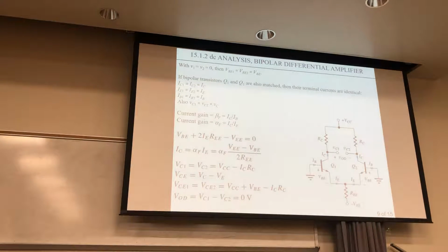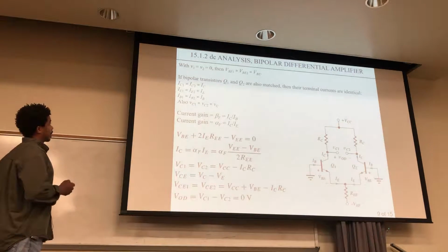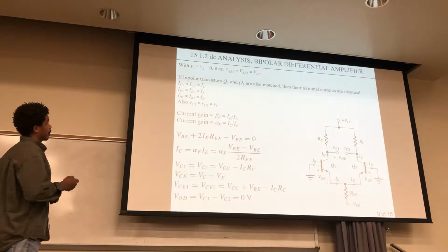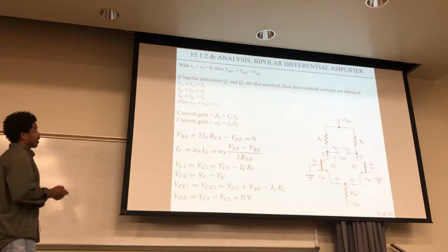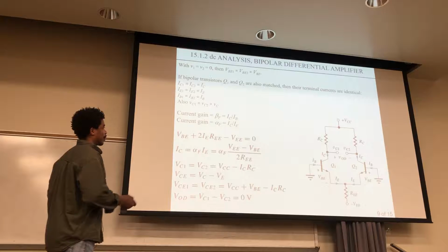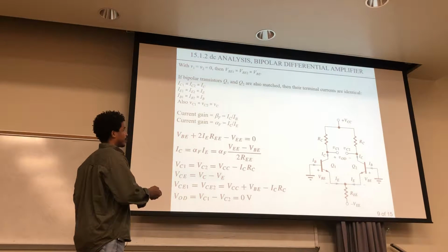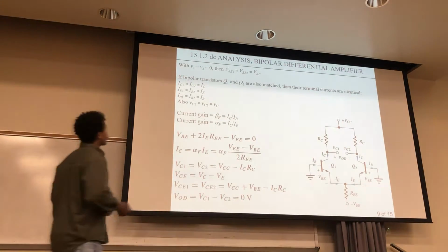Okay, then after you do that, a few things pop out of that. What you get is that VBE1 and VBE2, we'll set those equal just to VBE. Those are all the same now. So we're talking about these right here. This was VBE1, that was VBE2, and now they're identical because these are both grounded. So the voltage going from here to here is shared. That voltage is going to be common to both, and that's why you could say that these two things are identical.